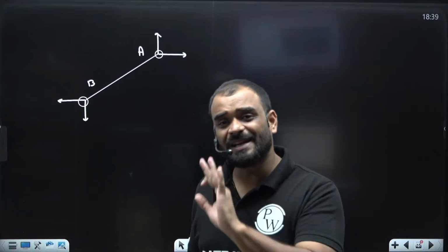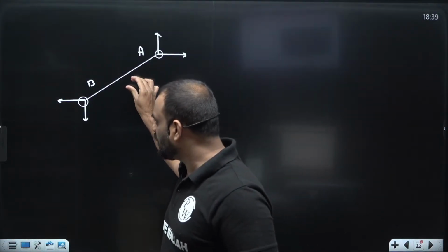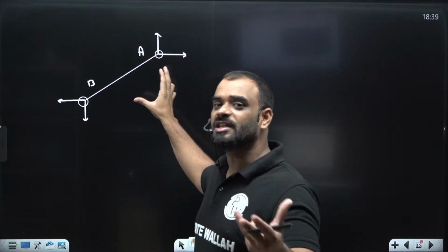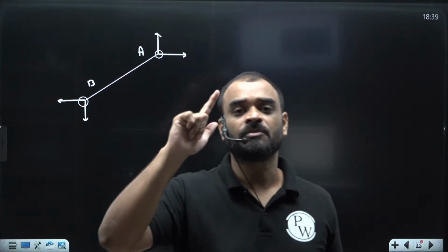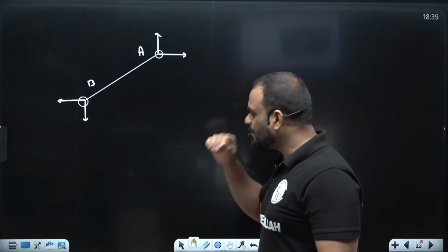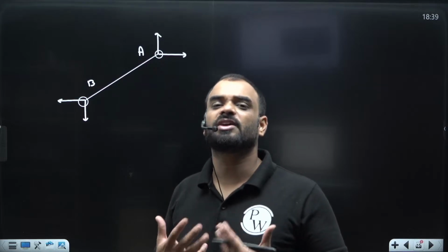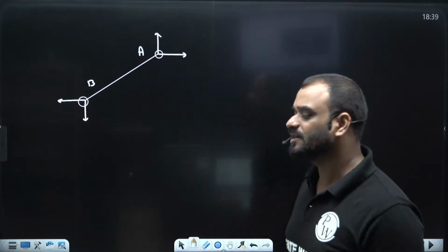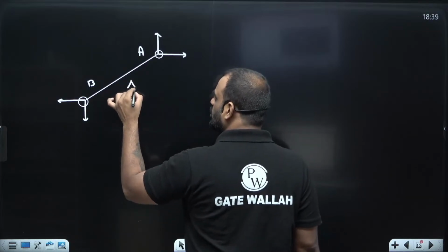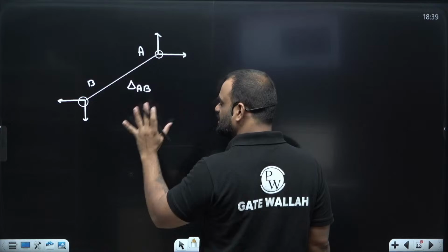Now due to this reason, the length of the member AB is trying to change. If the member length is trying to change, then definitely it will produce some force. Because we know that guys, whatever member you consider in a truss, all the members take only axial force as an internal reaction or internal force. So guys, if some change in length of AB is present, then only the force in member AB is present. Why?